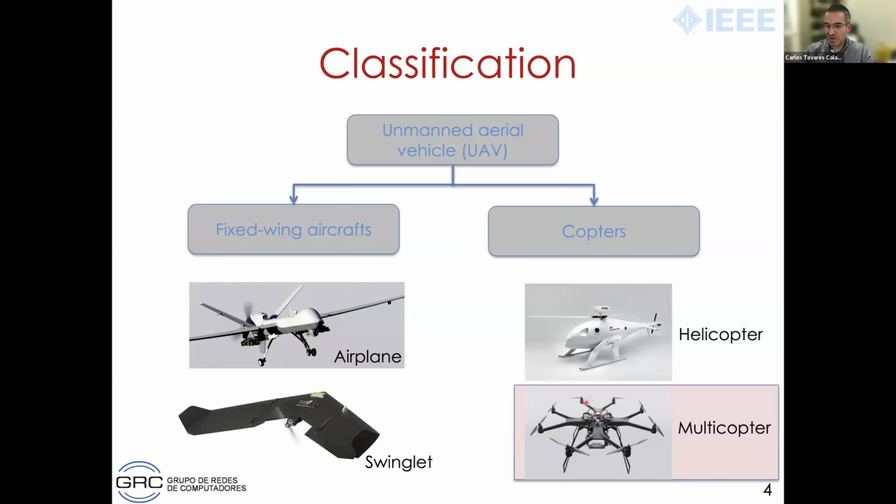So if you need UAVs to fly for a very long time, then either you go for these hybrid solutions where you have a combustion or hydrogen engine in addition to the energy systems, or you directly have a cable connected to the UAV and you are limited to missions within very few meters around your location. So as of today, we don't have any other solution to extend the flight time that actually works.